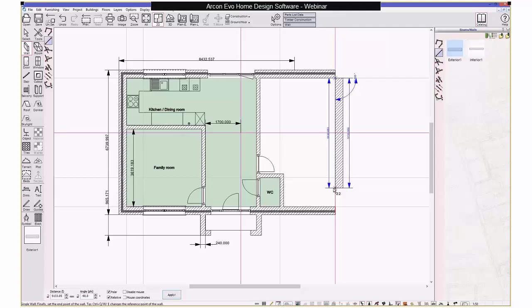You've also got numeric inputs. You can obviously enter walls numerically. You could also, if you've got an existing plan, for example, from a DXF or DWG file, or from a drawing as an image file, a JPEG or a bitmap, for example, you can also import that in, and that works as a background where you can overlay and draw over top of the actual background layer. So you can very quickly draw out your plan using a background image. So what I'm going to do is just draw this external wall position.